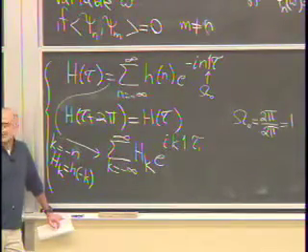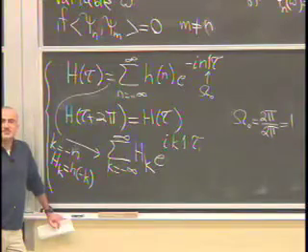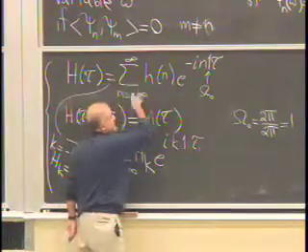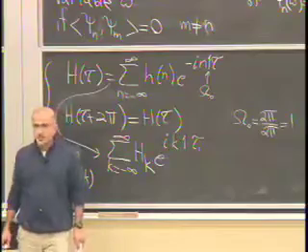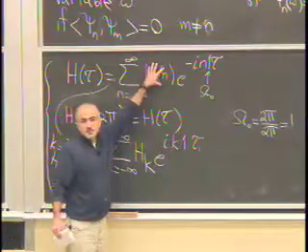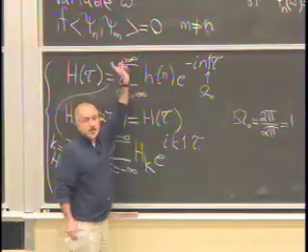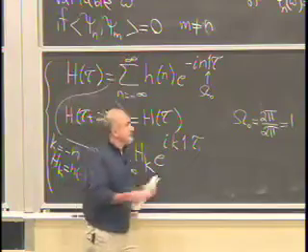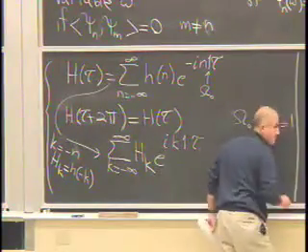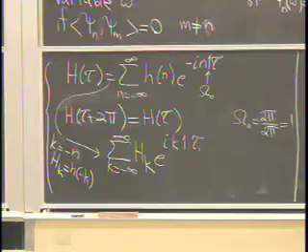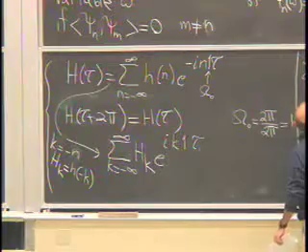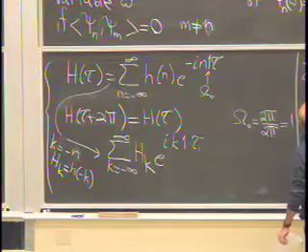Yeah, exactly. So there is an assumption I'm making about the signal or the function small h. This summation, anytime you have an infinite sum, you've got to worry about convergence. And not every discrete time signal or function will have a Fourier transform. The underlying assumption throughout everything I'm about to say, both for the discrete time Fourier transform and continuous time Fourier transform, is that in this case, I'm assuming h of n is absolutely summable.